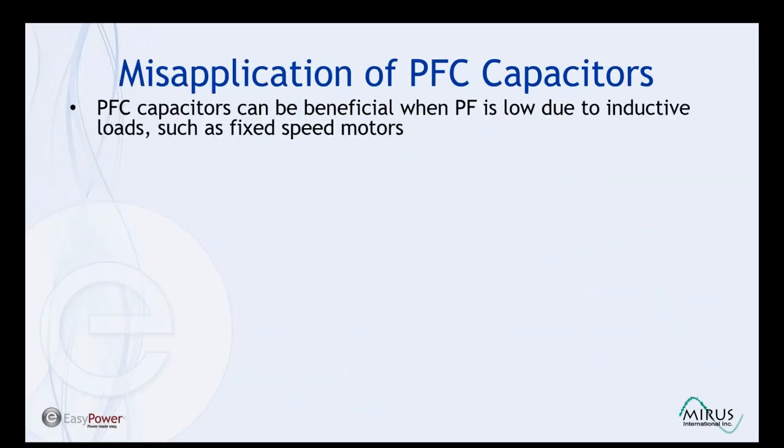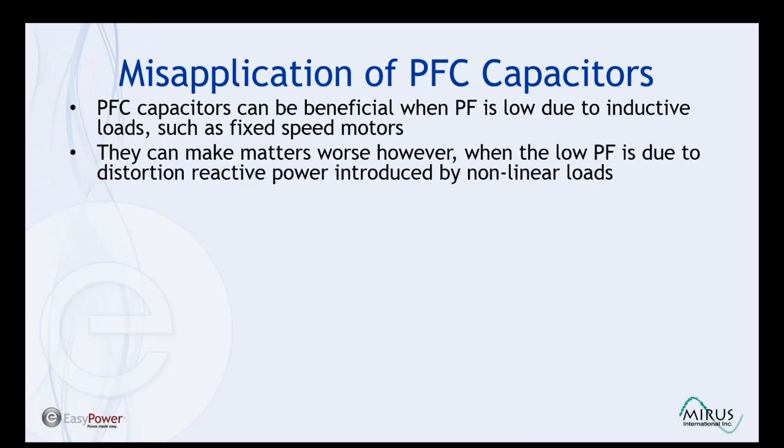What happens, though, when the low power factor is due to harmonic kVARs and not inductive kVARs? Power factor correction capacitors, which can be beneficial when applied to inductive loads, such as fixed-speed motors, can make matters worse when applied to nonlinear loads.